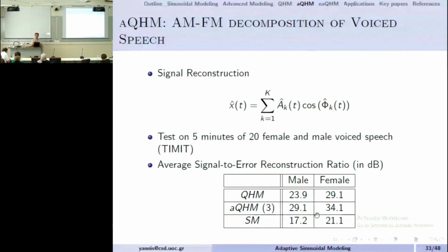But it is high resolution, with K components, where K can be like 80. So it is a high resolution AM/FM decomposition of speech or audio with a parameterization of the AM and FM, which is under control. I can control it now. It's not like with Hilbert, where you get another signal and wonder what to do with that. Here I have full control of my A_k(t) and phi_k(t). In short, we improve the analysis and we do AM/FM synthesis as we do with the sinusoidal model, but we have a better analysis.